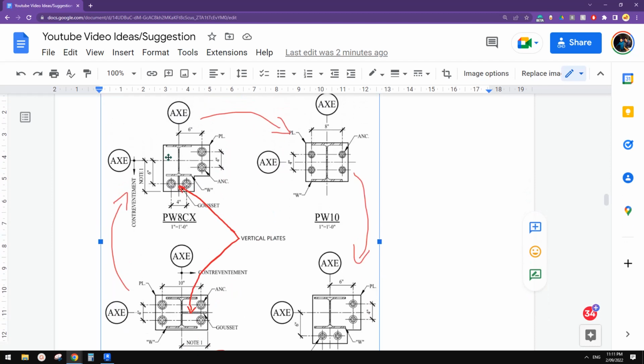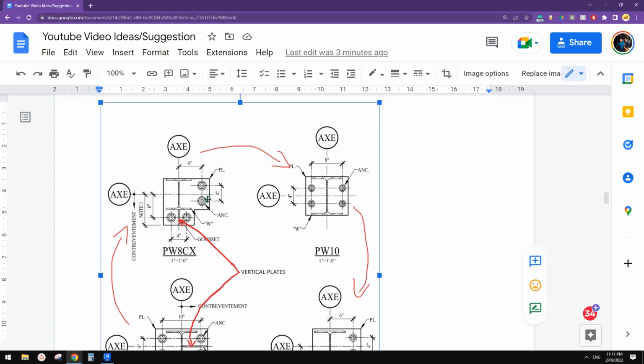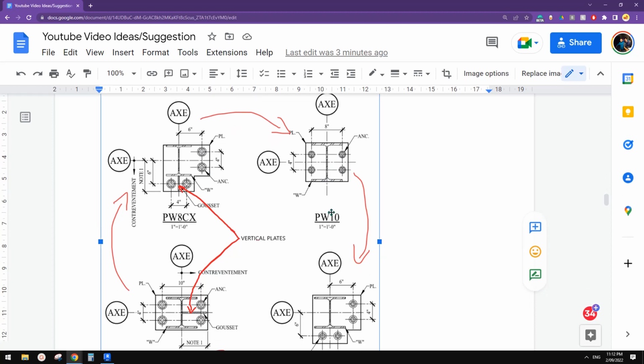Imagine you just build a plate here, and then build another one, and then you can use a visibility parameter to control them on and off. So I think this is the easiest way to do it. Another option is you can model this family as one family, and model this one as another family, and then you can just place them together in one file. You can create a label parameter, so we can have a drop down menu to choose options.